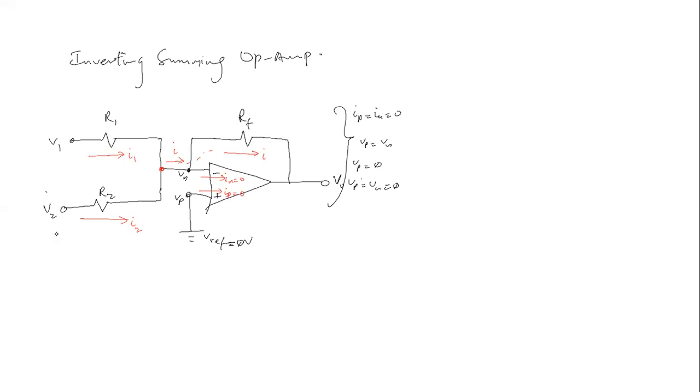So by Kirchhoff's current law, the current flowing out of a node is the same as the sum of currents flowing into that node, I sub 1 plus I sub 2. And then by Ohm's law, this expression reduces to I being the same as I sub 1, which will be V sub 1 minus V sub n by passive sign convention, positive, negative, right?